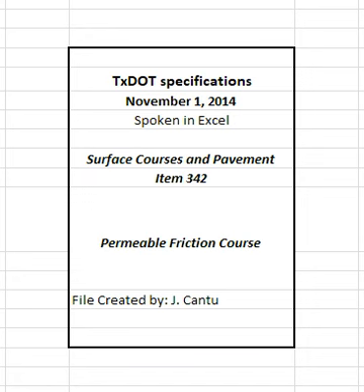Control the mixing time and temperature so that substantially all moisture is removed from the mixture before discharging from the plant. Determine the moisture content, if requested, by oven drying in accordance with Tex-212-F, Part 2, and verify that the mixture contains no more than 0.2% of moisture by weight. Obtain the sample immediately after discharging the mixture into the truck, and perform the test promptly.